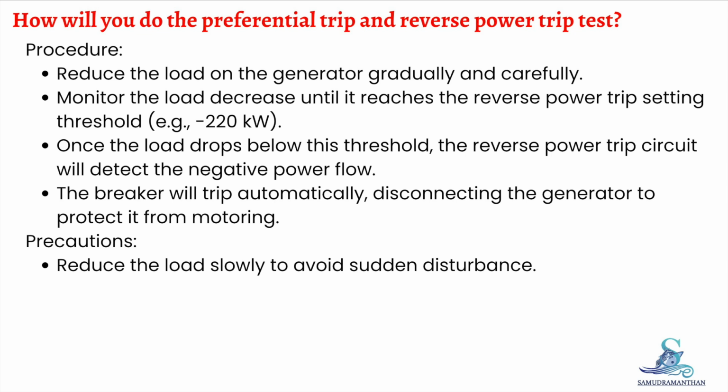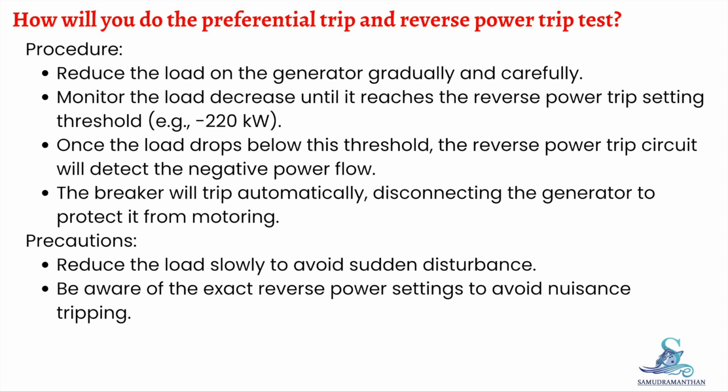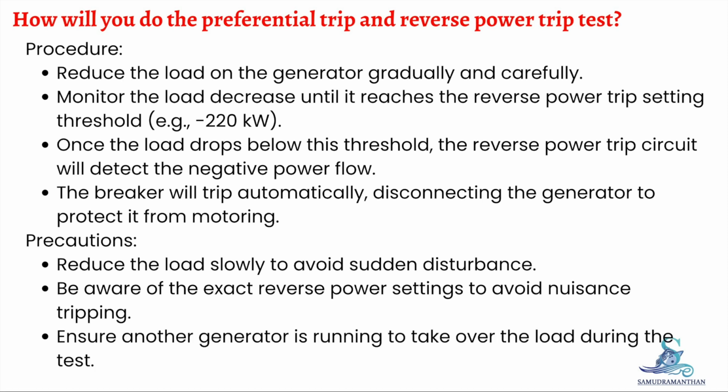Precautions: reduce the load slowly to avoid sudden disturbance. Be aware of the exact reverse power settings to avoid nuisance tripping. Ensure another generator is running to take over the load during the test.